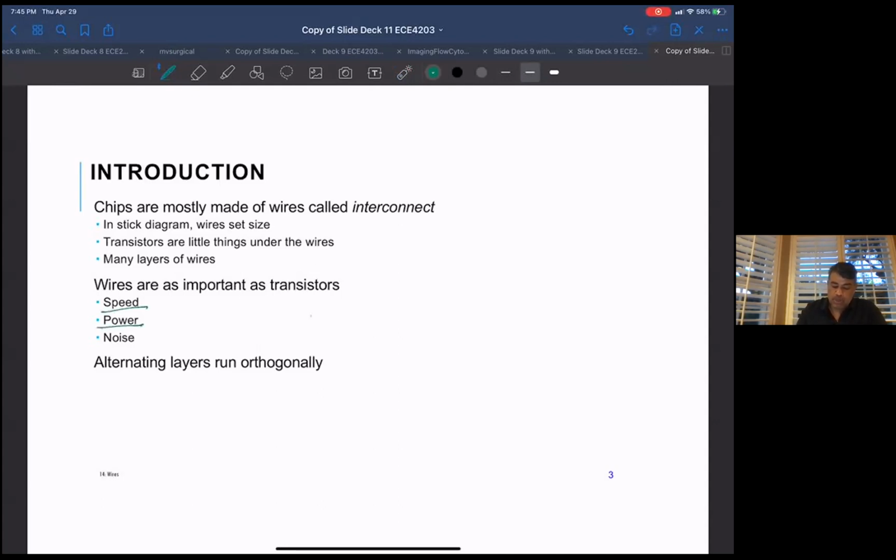Power consumption, we saw that it's all about CV squared F times an activity constant. If we add the capacitance of the wire to our load, especially in some nodes like the clock, imagine a clock signal getting routed all over the chip, the capacitance of that node tends to be large. So it will affect the power consumption significantly.